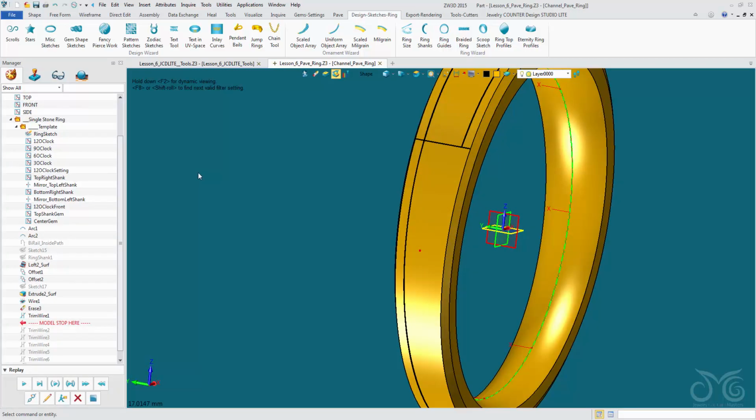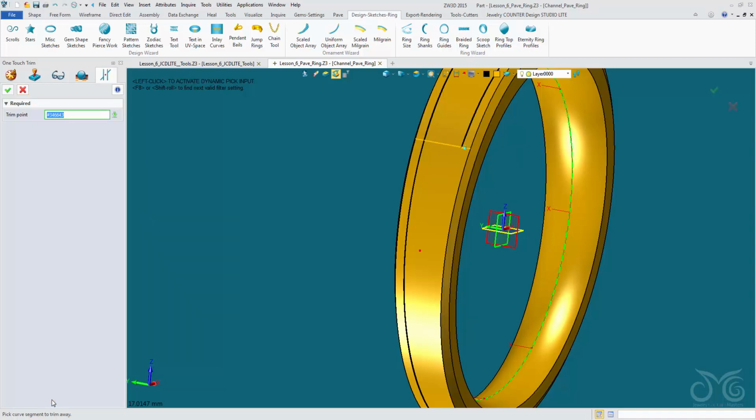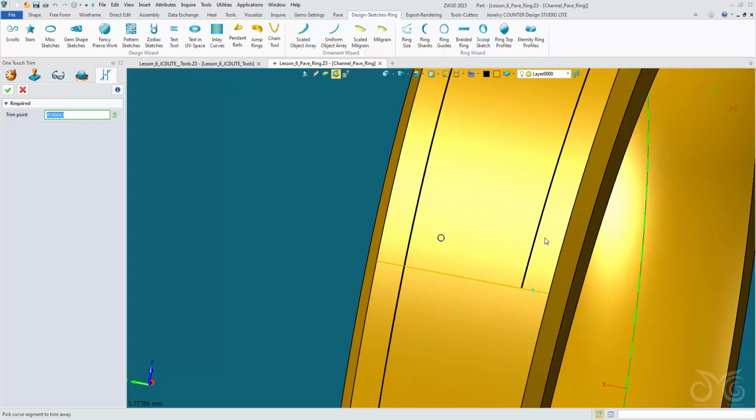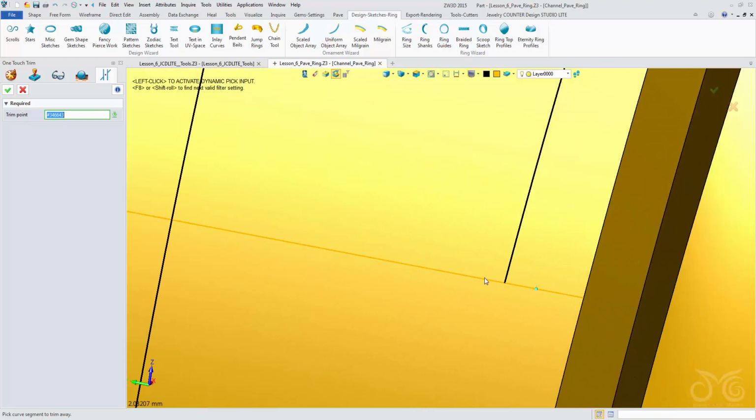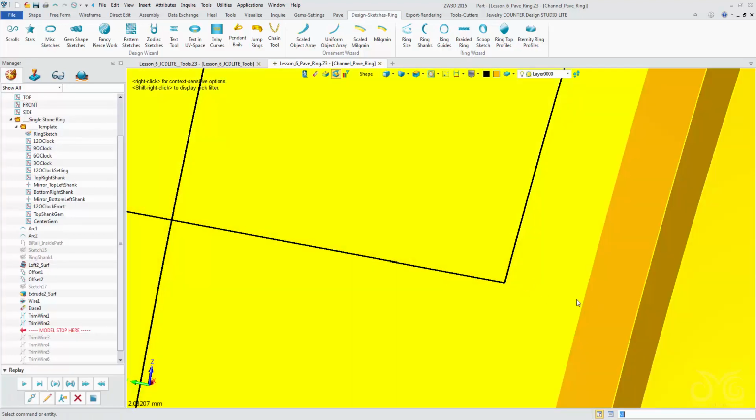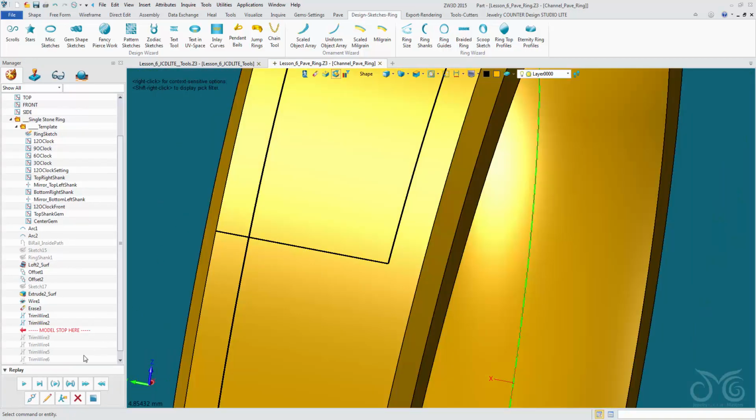Okay, so this is how we should do our designing, so that when we come in to make modifications to our design, we aren't throwing off the rest of history. But in this case, say we change the offset, we brought the offset in a bit, our pick point is going to be on the wrong side. So we again use our along here, and let's just go along an insignificant distance, 0.1 millimeters. I mean 0.1% of this line. Okay, it's going to be right here. So it's always going to be the right side of that line that we're using to trim.